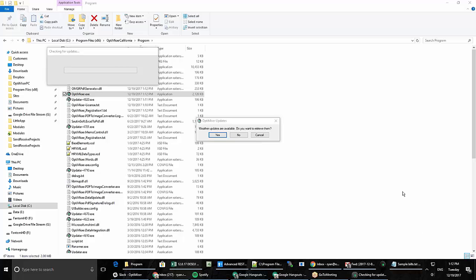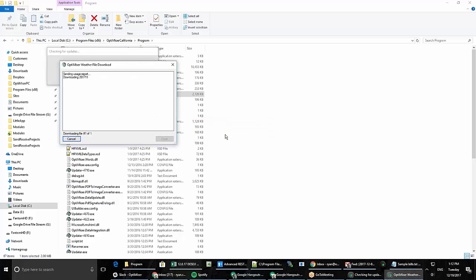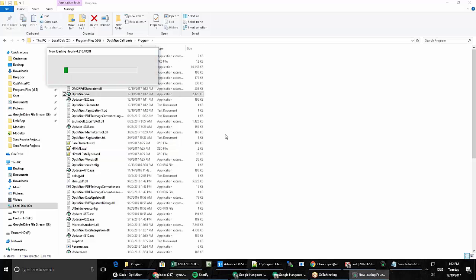So Cake is a regression based tool, and OptiMiser and Snug via OptiMiser are physics engines. It's actually a hybrid degree day hourly model under the hood to keep track of the gains and losses, energy flowing in and out of the house on an hourly basis, and it builds two models all the time. So as soon as you launch OptiMiser, you have a base building model and an improved building model,